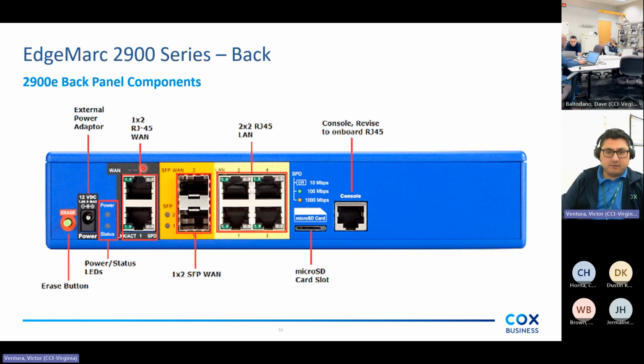You have 2 wide area network ports, or 2 WAN ports. Port 1, which is the bottom port, and port 2, which is your top port. Your backhaul goes to port 1. When we do the configuration, it also only configures port 1. We do not use the SFP ports for WAN 1 or 2.